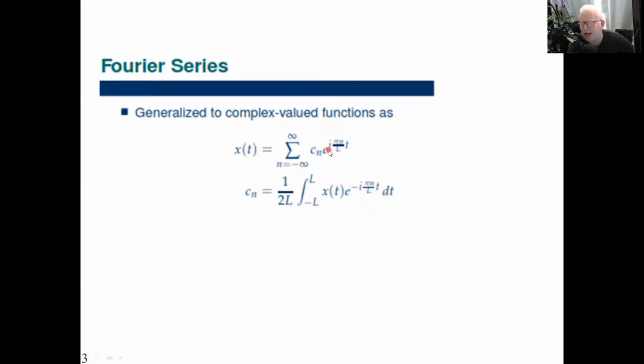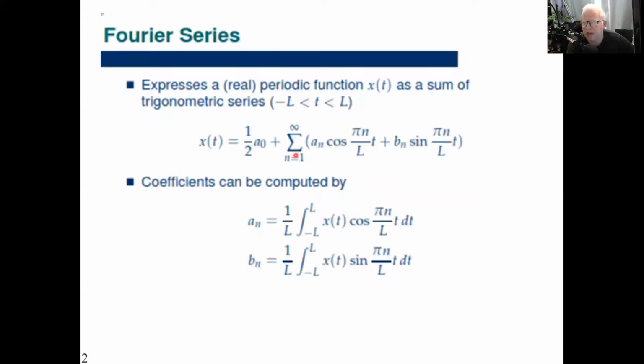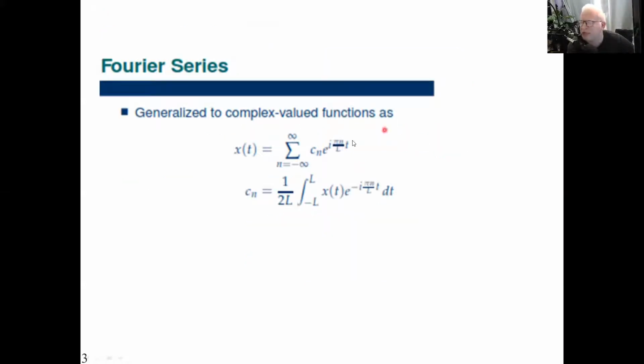This is actually a very simple trigonometrical change, because you simply know that this exponential with an imaginary coefficient can be expanded into cosine and sine signals. So this is just a trigonometrical formatting of the equation, either in terms of the sinusoidal coefficients an, bn, or in terms of an exponential coefficient Cn. So this is how the Fourier series works.